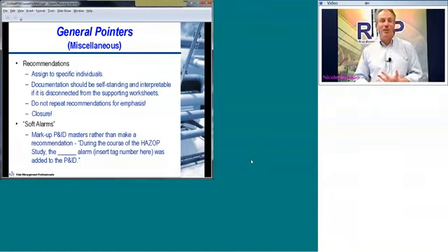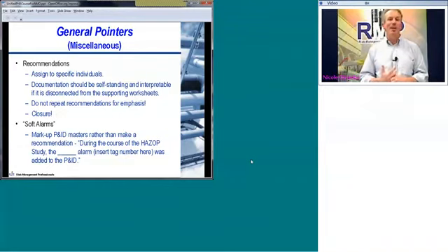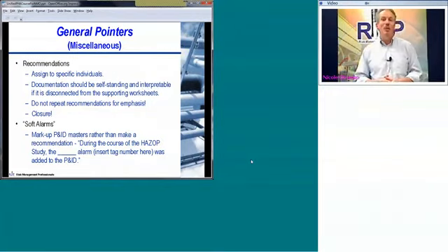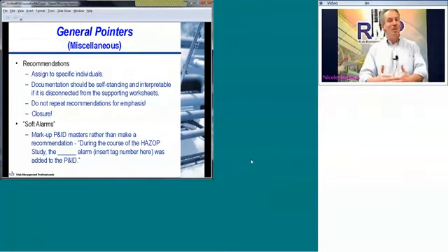I see this all the time when we pick up somebody else's HAZOP study to do a revalidation. You see the same recommendation over and over and over again. That doesn't help anybody. All it does is make additional action items on the tag list and make it look so big that nobody wants to work on it. A good way of addressing this is to make a recommendation once, in the most important place if you can, but at least do it once, and then in the other scenarios that reinforce the need for that recommendation, just make a cross-reference note rather than an additional action item. Also, for recommendation closure, make sure it's set up so that people at the plant site can get to them and close them in time.